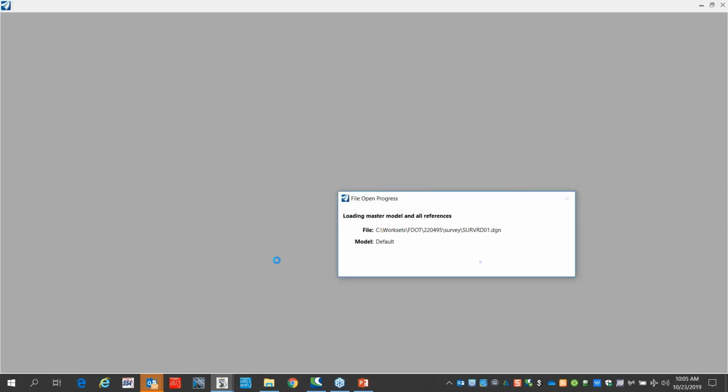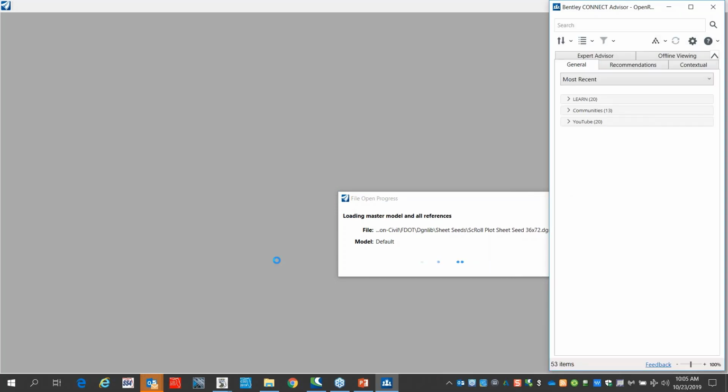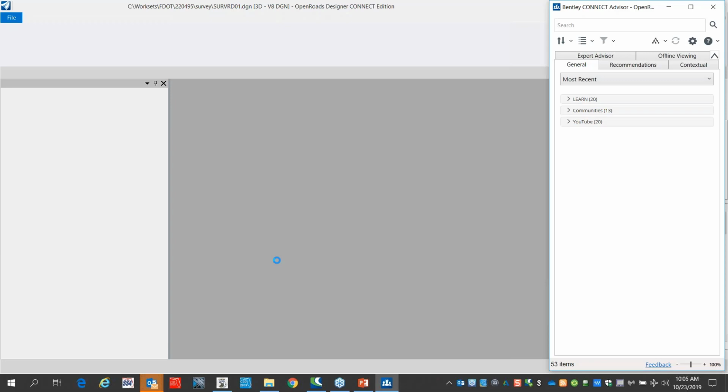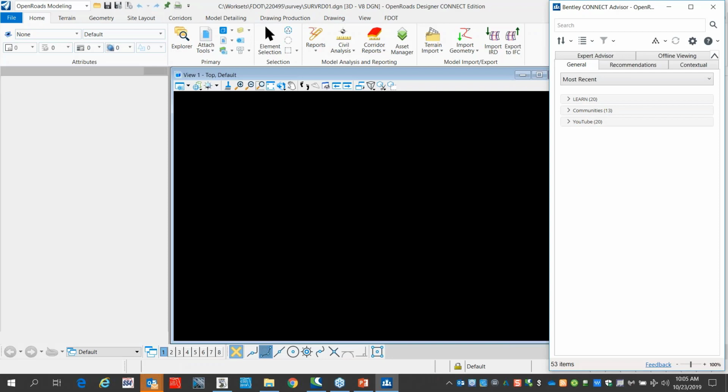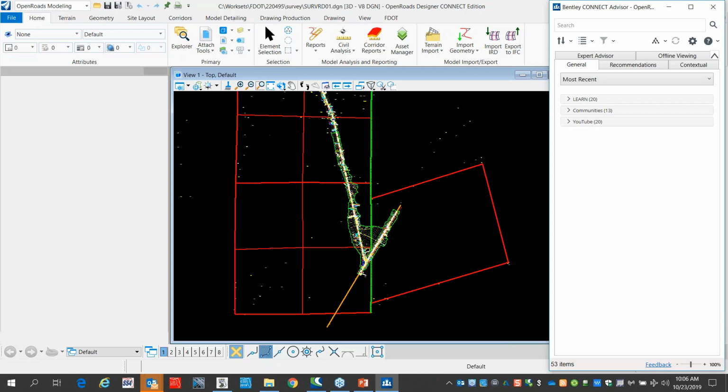And one of the things that's important to note is that when you are in the survey itself and you're looking in through the field books and digging down through the categories, they're almost organized like folders, but they're the categories of features. You can visualize independently each of these features, and you can also show the chains, the actual details of the chains or the details of the points by selecting them. And you can do it two different ways.